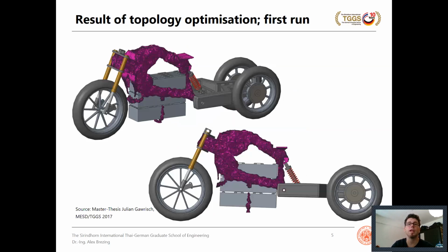In this case, this is put in, and this is the result that the topology optimization process, the FEM software, gives us. And it looks kind of neat. It looks like something that Swarovski might have designed. It looks very crystalline, and this, of course, is because it's using the typical mesh of an FEM model. So what the software does, it meshes the design space as it would do with any structural simulation, and then these elements are more or less removed. Mahathep will talk more about this.